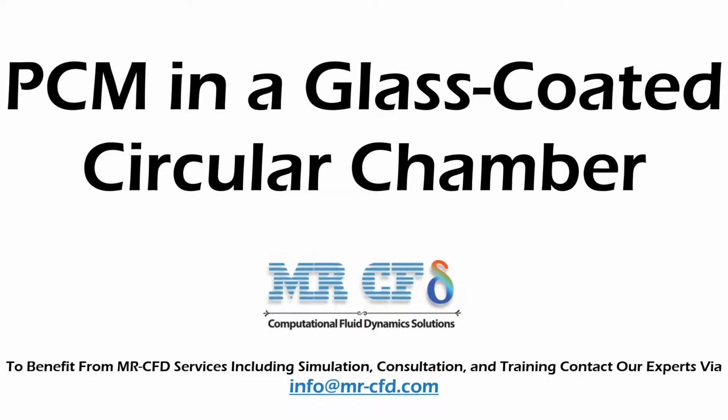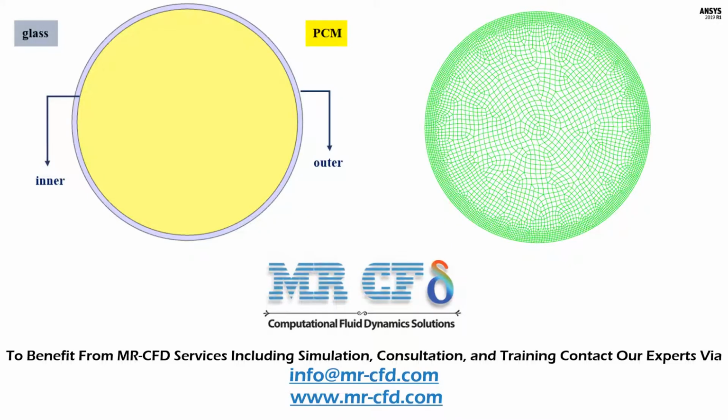The present problem simulates the performance of a PCM in a circular chamber with a glass cover. The two-dimensional geometry of the model is designed using Design Modeler software. Also, the meshing of the model has been done using ANSYS meshing software, and the mesh type is unstructured.